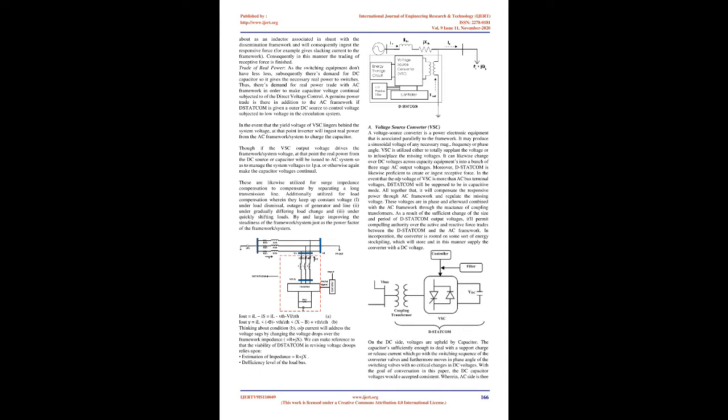The inverter consists of a capacitor as the DC input source. IGBTs are the best switching devices not only in the power electronics field but also in distribution systems, and the controller circuit provides the gating signals for on and off control. The injection of the waveform is because of the high-speed switching of the VSC, which synthesizes a 50 Hz to 60 Hz signal using pulse width modulation, PWM.